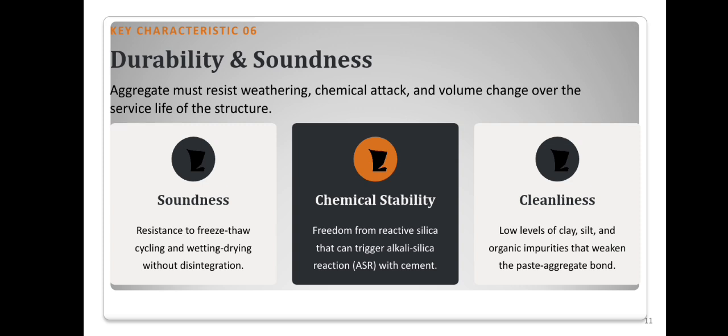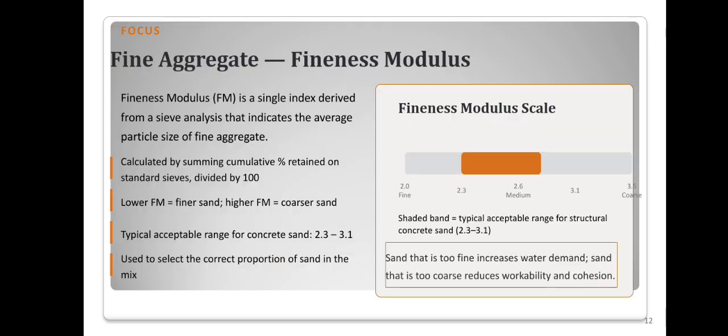Aggregates should also possess good durability and soundness. They must resist weathering, climatic and chemical attack, and repeated wetting and drying. Clean aggregates free from clay, silt, and organic impurities ensure a strong bond with the cement paste and improve long-term durability of the concrete. Two practical concepts are also important in mix design.